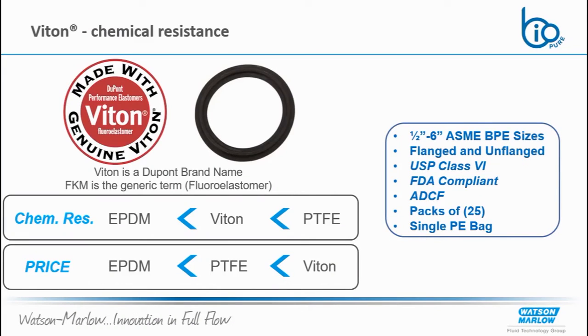And finally, Viton. Viton is a rubber compound as well. It has superior chemical resistance compared to EPDM, and while it's not as commonly used as EPDM, this is an option for applications where harsh solvents or cleaning chemicals are being employed. So you would expect to find this more in small molecule or API applications.